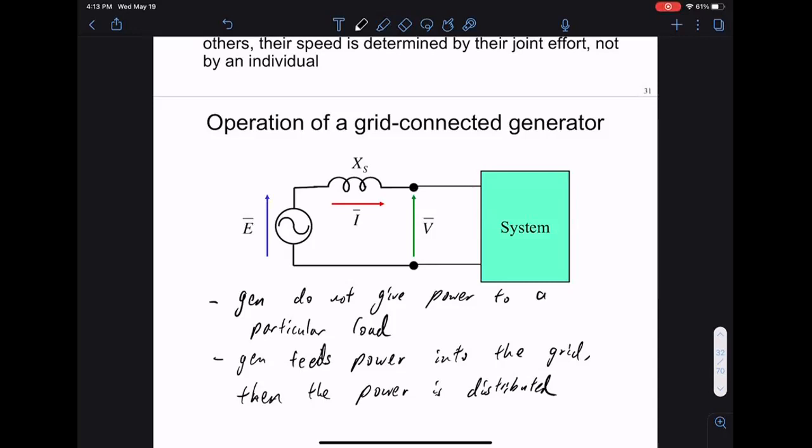So if Texas had another blackout and, down the road, wanted to connect to the east or west power grids, would they even be able to do that, since they're maybe slightly off on phase angle or on frequency? No, so once you build enough lines, you're naturally balanced, right? If you have enough transmission lines, you'll balance. Few transmission lines is bad because those few lines cannot synchronize two huge grids. But if you give me 10 gigawatts of transmission lines between Texas and the Eastern Interconnect, sure, they can synchronize. It depends on how many lines they want to build. Building a few lines will not do much. But with massive infrastructure building between Texas and the other interconnects, sure, they can synchronize.